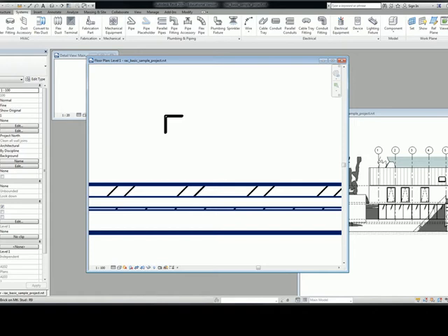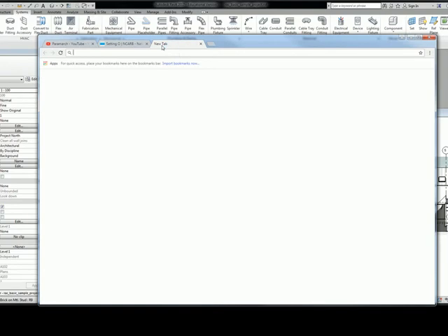And when we put all this stuff together, like the duct run that goes to this versus the mount connection to the structure above that, right? If the duct's going across that way, and then the structural connection for the projector is in its way, you can run a clash detection in like Navisworks or something like that. Revit doesn't do the clash detection, unfortunately. But it will tell you. It'll literally spit out a list that says you have these 1,112 things that you need to fix. Right? It's pretty amazing. So real quick, I'm just going to jump into Google and show you what clash detection is. So we were talking about that.